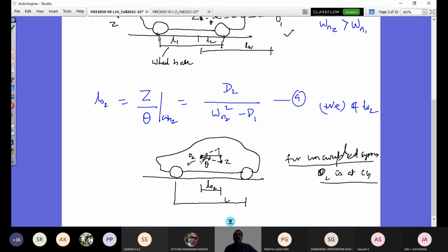But in the coupled system also, unlike these two cases that we have just seen, O1 and O2, if those oscillation centers disappear, I will have only two single degree of freedom systems, with my equivalent vehicle rigid body as two masses sitting at the front suspension connection point and rear suspension connection point. That would give a good ride model.